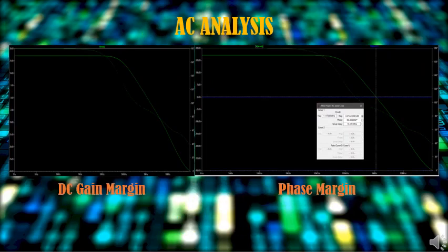For AC analysis, this is our waveform that we got. So after plotting the V out, the graph is the same as the reference, but the value of gain is different. After that, to check the phase margin, I plot one more graph which is V in positive. Then we put the cursor at the intercept of V in positive and V out. So we got the phase which is 90 degree.